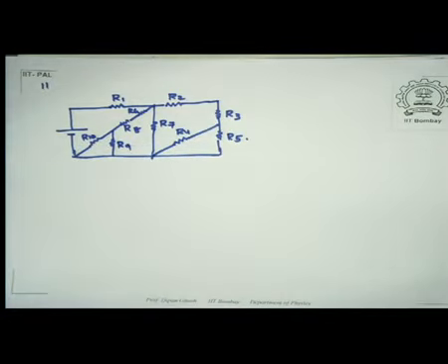Doesn't look like a series or parallel combination, but let us try to look at this a little more carefully. So, all that I need to do is to observe whether the same current is passing through or is the same voltage between two ends. If it is the former, it is a series resistance. If it is the latter, it is a parallel resistance.